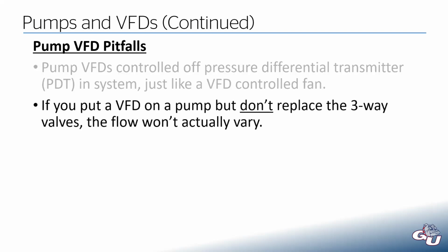So if you put a VFD on one of your pumps, assuming it's a constant volume system and it has a bunch of three-way control valves, just because you stuck a VFD on the pump doesn't mean that that pump is going to do anything if you don't replace the three-way valves that are out in the system.